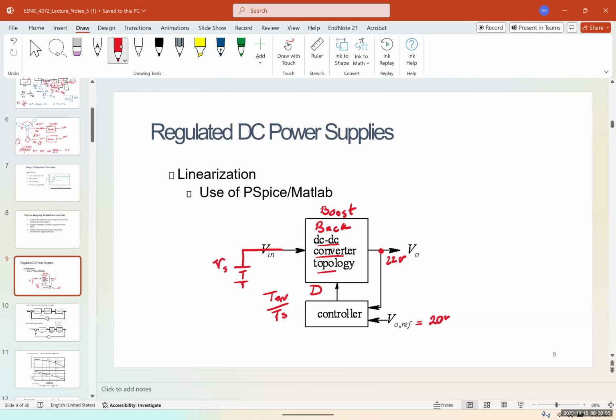Now these two graphs, the upper graph shows the loop gain magnitude at the phase margin FC. As you can see, at FC it's 0. And it also shows the gain margin, which is around negative 40. By the way, this is in dB. And in the lower graph, we can see the loop gain phase. Again, we have the phase margin at around negative 90, not exactly negative 90, but around that. And then at negative 180 degrees, you can see the gain margin as well.